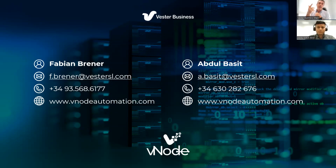That's number one. Number two, the payload inside the device, your PLC or whatever, usually, not always, you cannot customize the payload in these embedded devices. Sometimes you can, usually you can't. That means that if you have 2 devices from 2 different vendors, you're going to be sending to Amazon Web Services or your cloud platforms different payloads, I mean, different messages with different formats. So this is something you don't want.